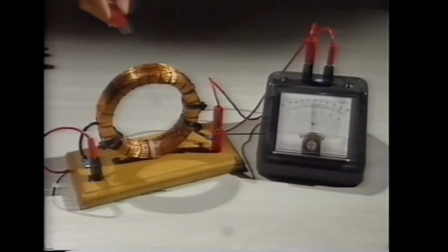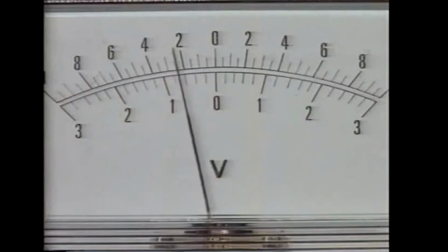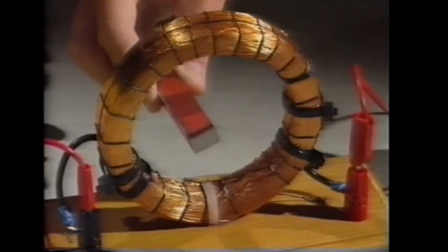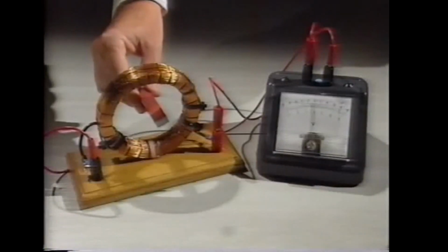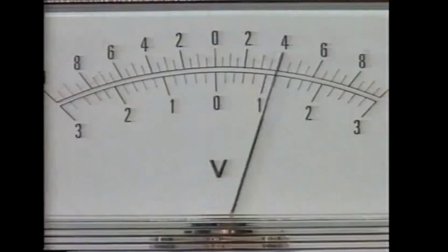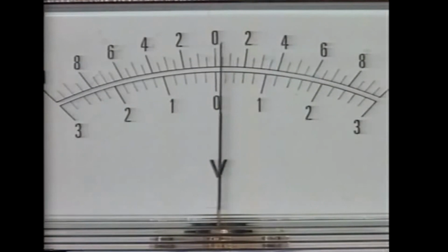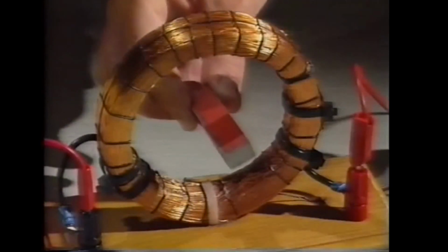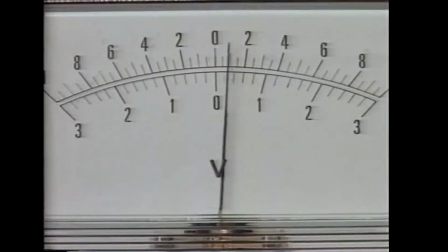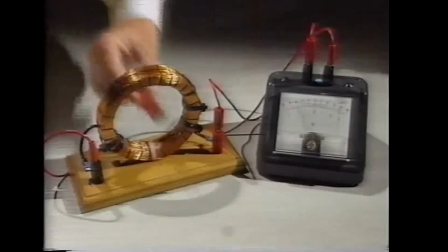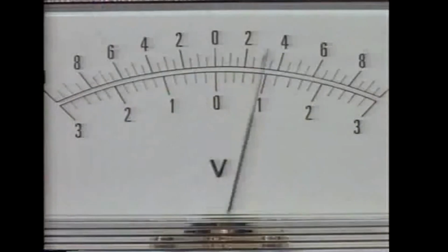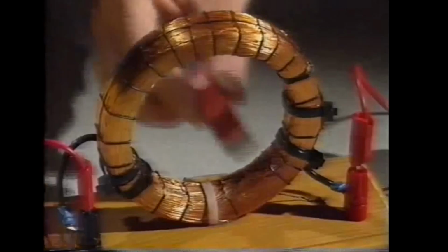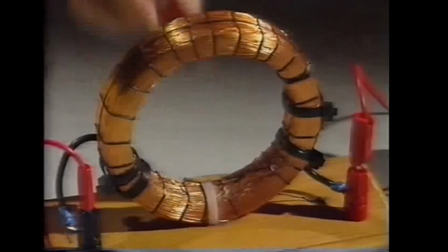When a magnet is introduced into the centre of a coil of wire, an electric current is induced in the wire, but only for as long as the magnet is moving. When the magnet is withdrawn from the coils, current is induced in the opposite direction. The faster the movement of the magnet, the bigger the current in the wire. If the magnet is moved rapidly in and out, the current keeps changing direction. It's an alternating current. This equipment is a simple generator.